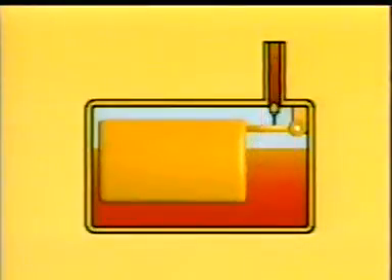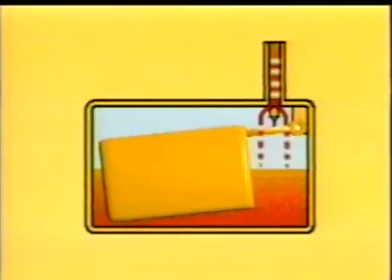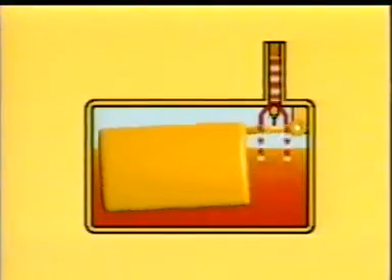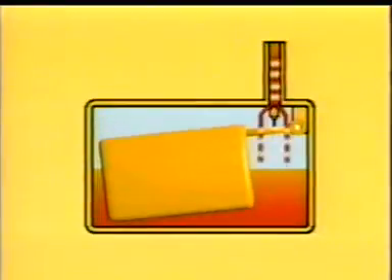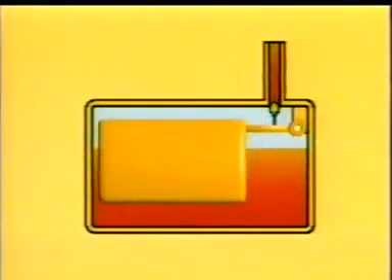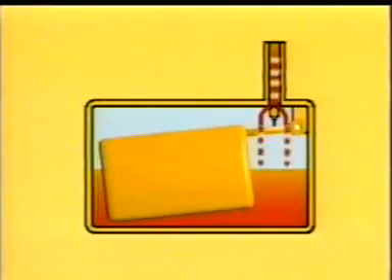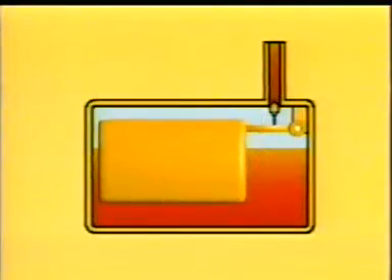When the fuel flows into the float chamber, the float is suspended on the fuel, and when it reaches a certain level, the needle valve closes off the entrance to the chamber so that no more fuel can come in. When the fuel level drops, the float drops also, allowing the needle valve to open so that more fuel can flow into the chamber. As the engine rotates, the float carries out this action over and over, keeping the float level at a specified position. This enables the amount of fuel sent to the venturi and the pilot outlet to be kept stable.